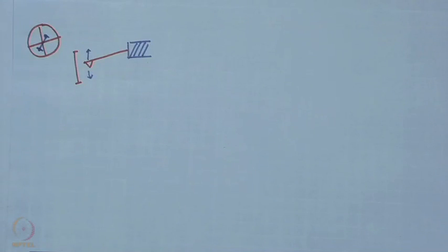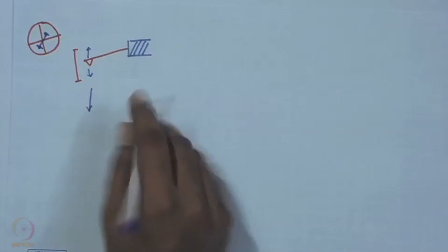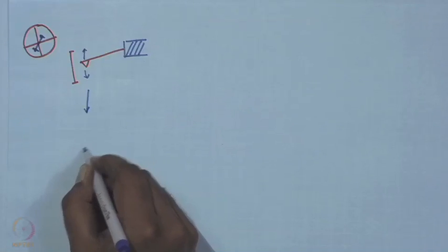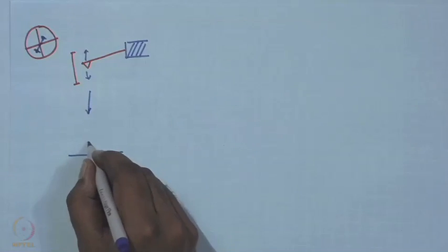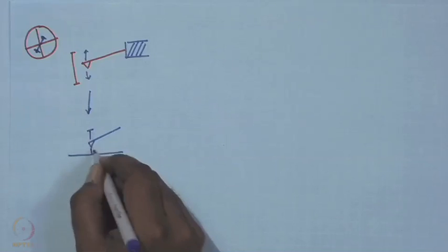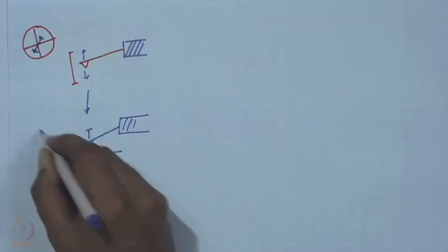So, what happens is as the cantilever comes closer and closer to the surface as it is oscillating, at some point it starts hitting or tapping the surface towards this end of its oscillation, and consequently on the QPD,